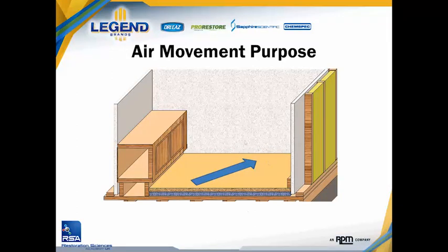Now, in an open field like this, like a floor, it's easy to understand how we can achieve this. There are many different types of air movers that are available in our industry that will allow for this. Where it becomes more interesting and more challenging is when this wet surface is within these interstitial pockets and voids throughout the structure. That's when air movement becomes a little more challenging, and we have to get a little more creative with what we're using and how we're deploying it. Because again, if there's no flow on these surfaces that are hidden throughout the structure, then we're not going to cause that reaction to occur at that surface.